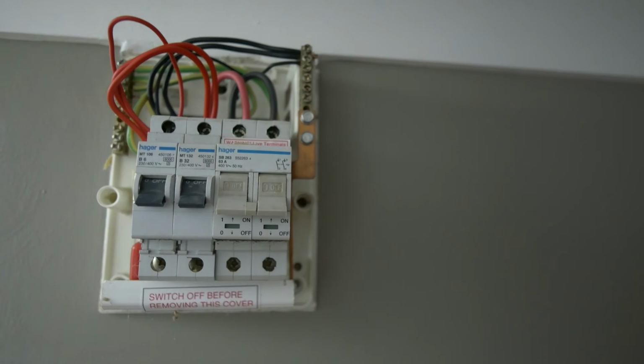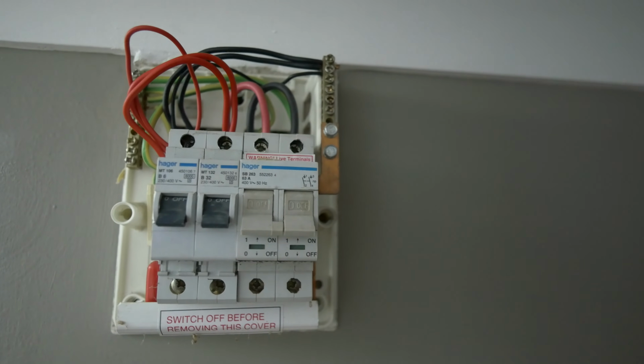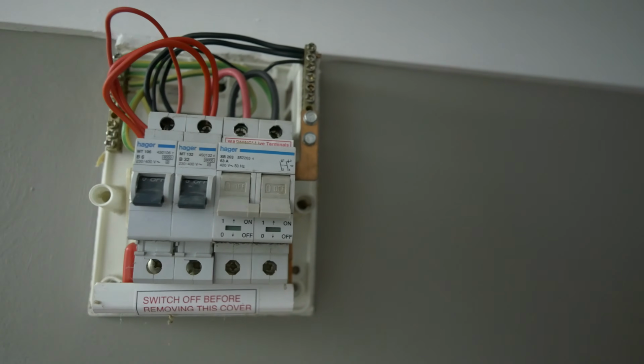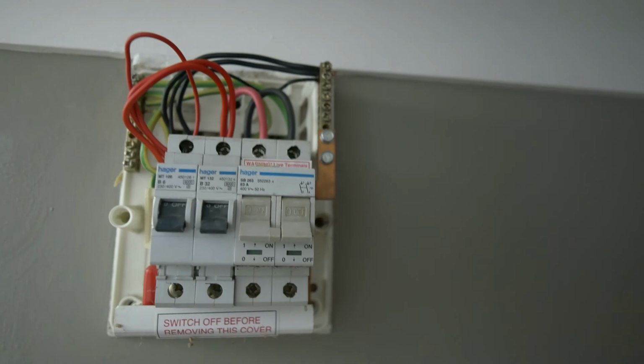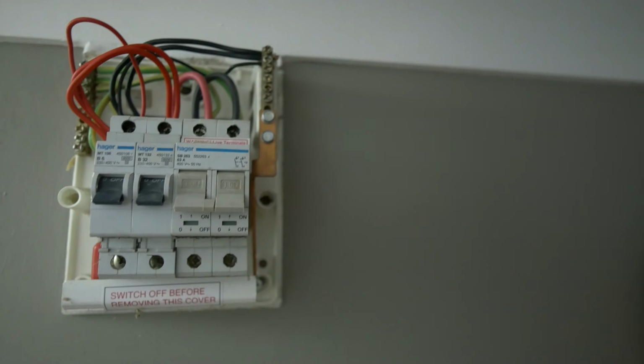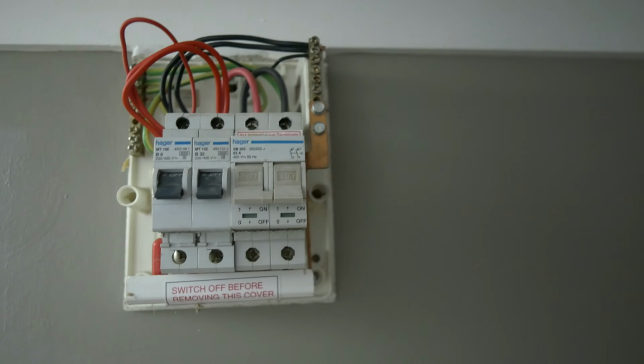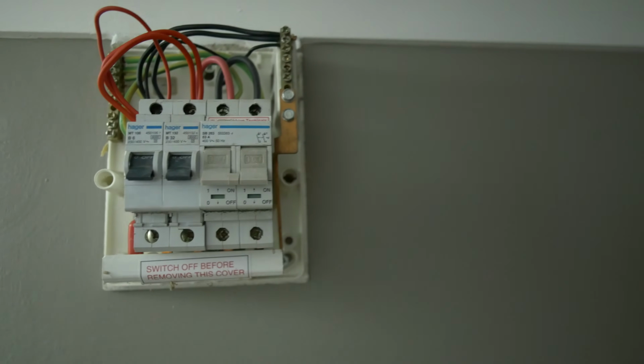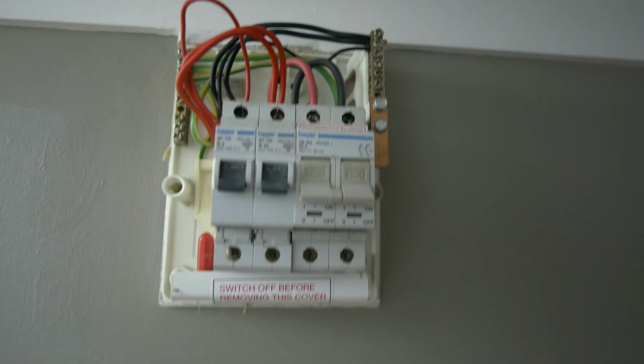Simple mistake to make, just rushing around putting terminations back in the wrong order, especially when you're a dyslexic old fool like me. And that's why I have processes in place to check myself once and twice and a third time. And we can put this all back together now, get energized and see what Zs values we've got on these circuits and how they compare to our dead tests.